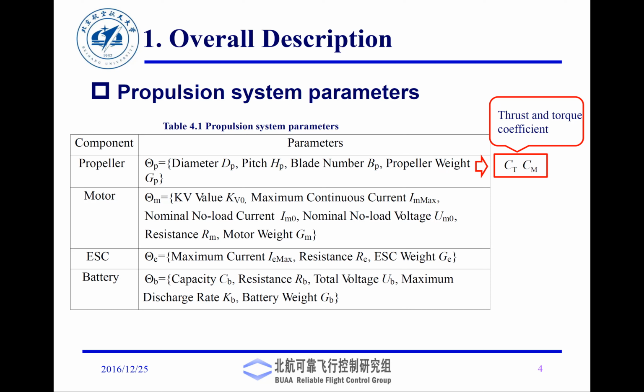What is the difference between a fixed wing aircraft and a rotary wing multicopter? In the fixed wing aircraft, you would notice that you change the angle of attack and you can get different values of lift and drag. At a certain angle of attack, the aircraft would stall. Why would a fixed wing aircraft stall? Because at that time, the airflow would separate from the airfoil. And when there is a separation, that airflow is useless. It will not generate lift.